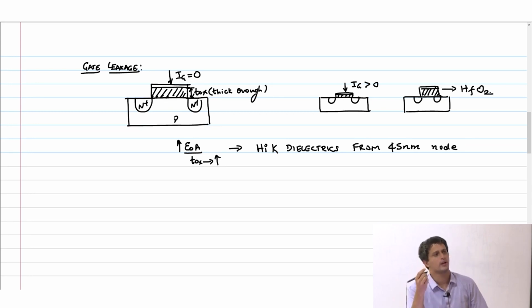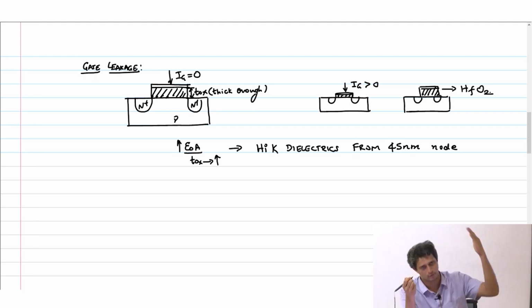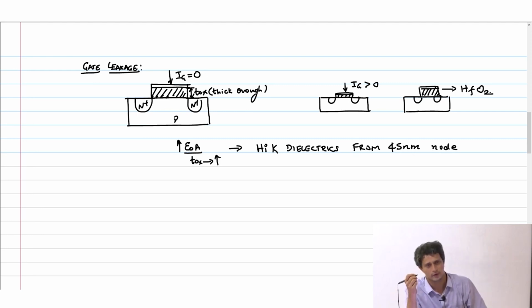It turns out that you can't put any material there because it has to gel with silicon very well. There has to be very few defects when you go from silicon to hafnium oxide and so on. So now the gate stack has become very, very complex. It's not just hafnium; in fact there are many more materials, so that you can smoothly go from silicon to this other material. This allowed you to get an epsilon R of about 12. The relative permittivity of hafnium oxide is about 12, compared to silicon dioxide, where epsilon R is 3.9 or 4.